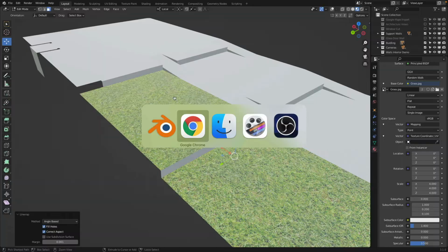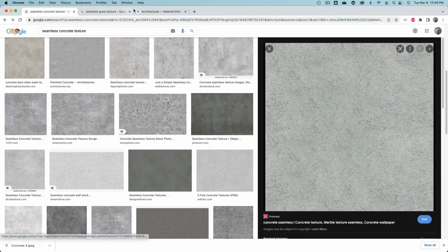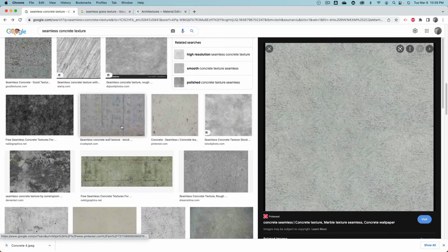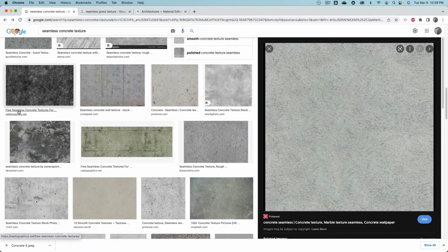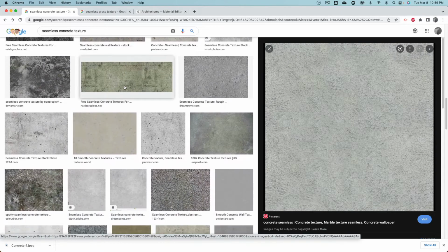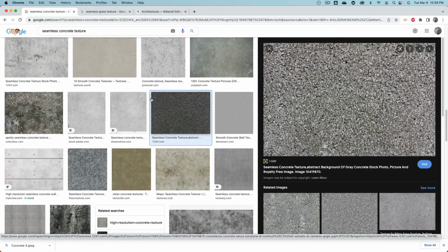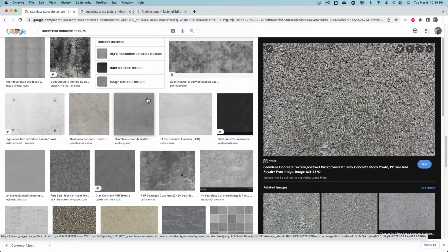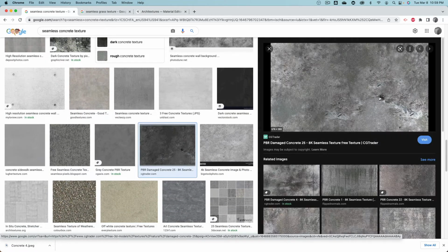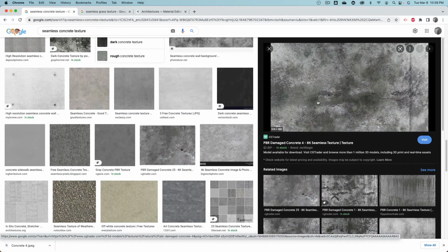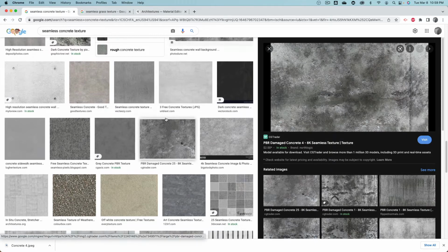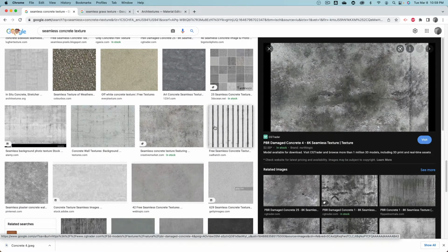Okay, so when you search for your own materials, you also want to find materials that, as you can understand, are not too detailed with repetitive elements. You want rather to look for textures which are nicely tileable. So this here will not be very good. These are okay if we map them as a single image over a complete wall, but we do not tile them.